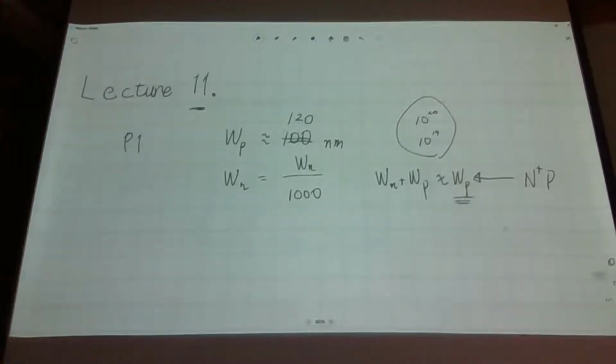And if we consider, for example, the opposite way, a p-plus-n junction, where we have a really strong p-type region, then you can say that the total depletion width will be determined by W_n. So we will only have a meaningful value for our n-type region. So only the relatively lowly doped region has the depletion region. Maybe you can remember this one.